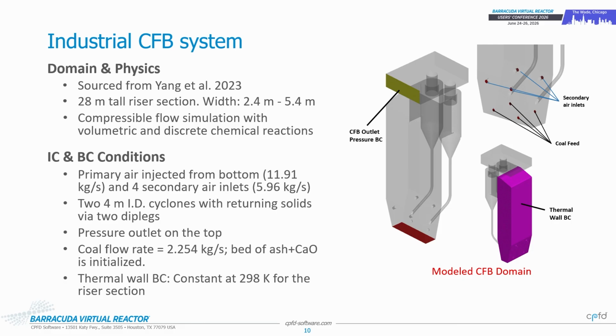All right, and that brings us to this 110 megawatt example. This was sourced from the Yang 2023 paper. This, once again, is that 28 meter tall riser, with width ranging from 2.4 to 5.4 meters. We use a compressible flow simulation with both discrete and volumetric chemical reactions.